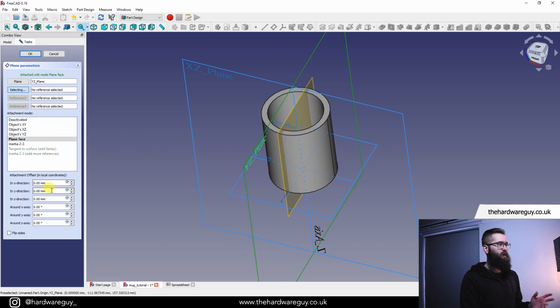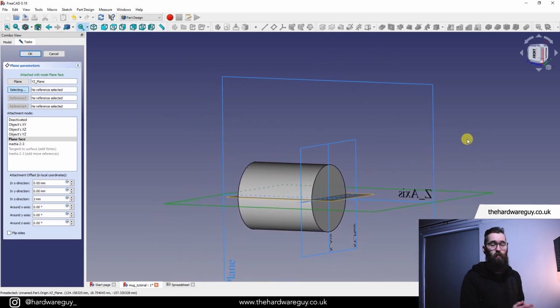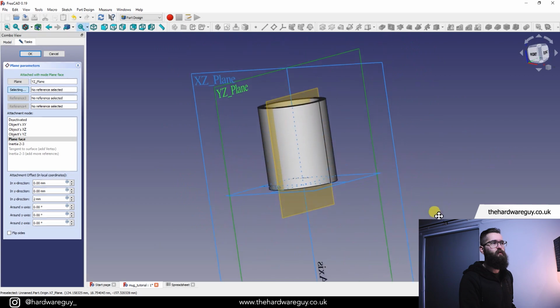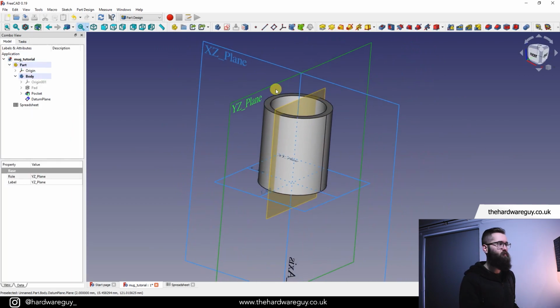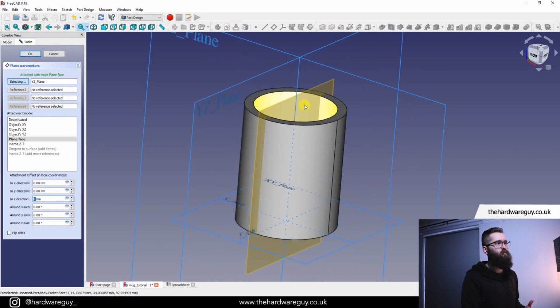In the tools here on the left, you will see we can move this plane around. If we go to the Z direction and play around with that, you can see that we can manipulate this plane and move it forwards or backwards. Now you might think this is a little confusing because the Z direction should be up, right? But these parameters always work in reference to the plane itself. So if you imagine you were looking at the plane from this orientation, Z technically now would be up in this orientation, and that's just how it works. It's a little confusing at first because you'd think it'd follow the coordinates of the entire workspace, but just remember that you can figure out which one it is by just playing around to see which direction it moves. But we do want to move it in that Z direction.